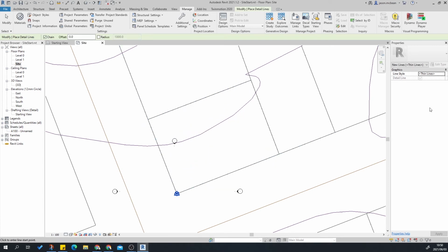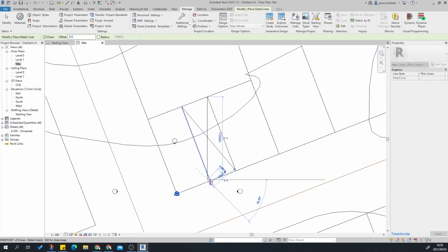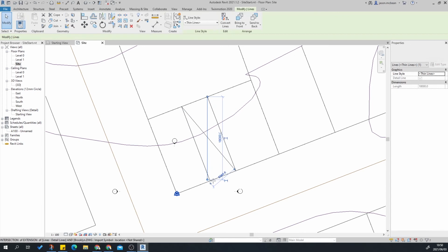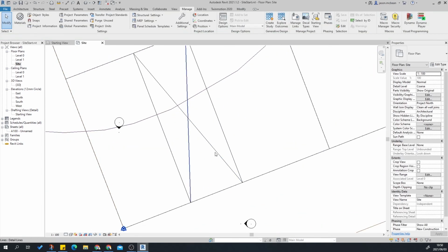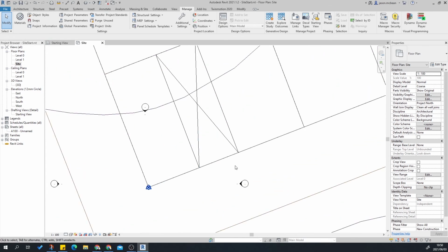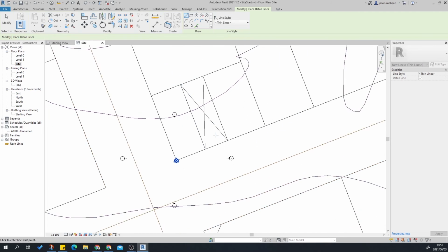That does happen, and that's why you want to change your project north. But I'm just going to use some quick line work. If my project was going to be located in this zone over here, we will move our project later on to meet the zone here. But you can see, if you had to keep working at an angle, this is not ideal because Revit is always trying to find horizontal, and you'll see it'll give us some text saying horizontal and vertical. So that's why we want to relocate a project.